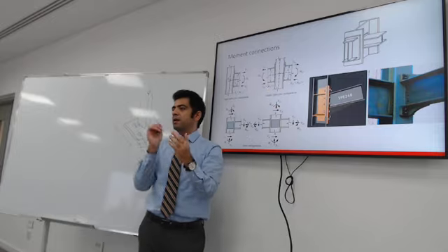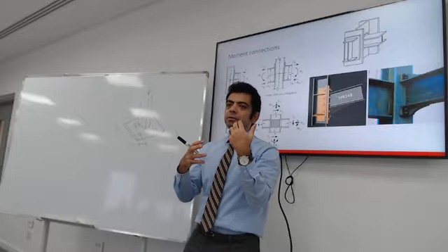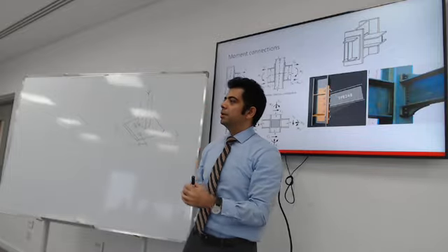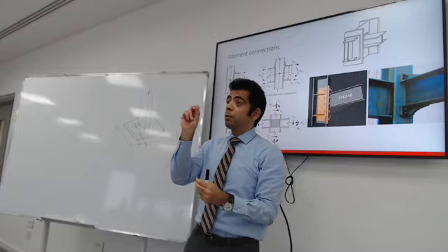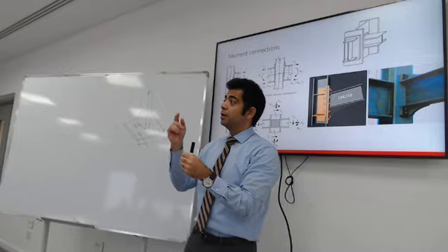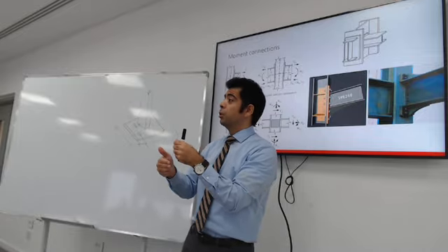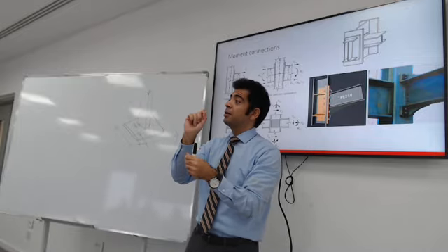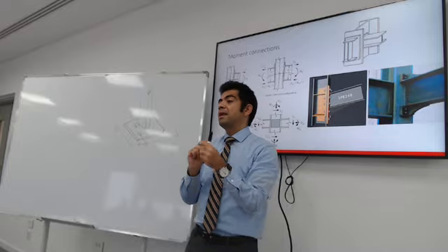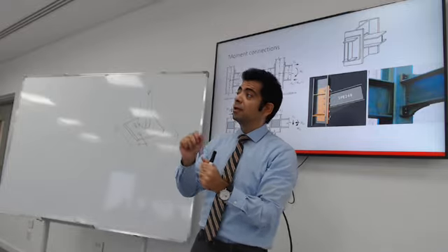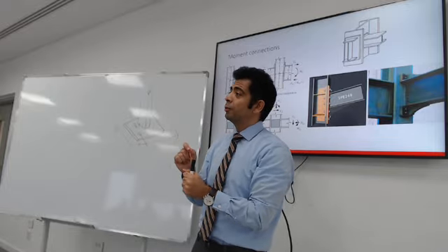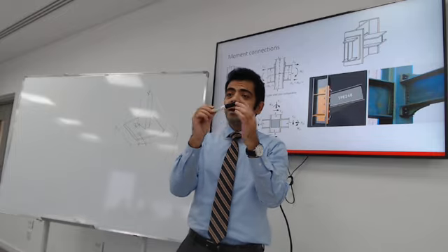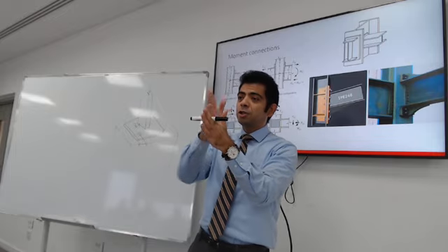in the tension side. So you break down the mechanism or the stability of your joint to figure out which bolts are facing shear, calculate the shear on each bolt, and calculate the tension on each bolt. And then check that the bolt can handle the tension or shear or both. What would you do if a bolt is experiencing shear and tension?